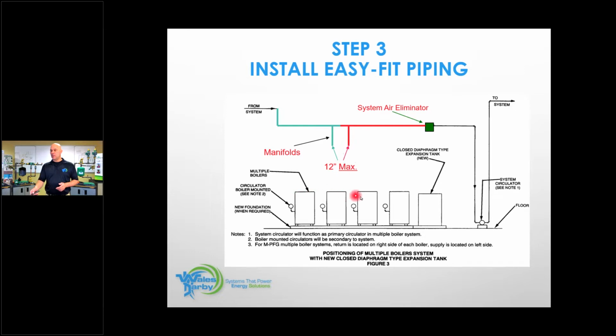And here we have 4 boilers. We're going to just tuck them into the supply in a reverse return pattern. So first in, last out. Okay, first in, the return on this would be last out. And this right here is a hydraulic separation point. So the circulator that's going to be mounted here on the boilers will not see this base mount circulator in the system, and vice versa. That's why we do primary, secondary T's, to hydraulically separate the two systems.